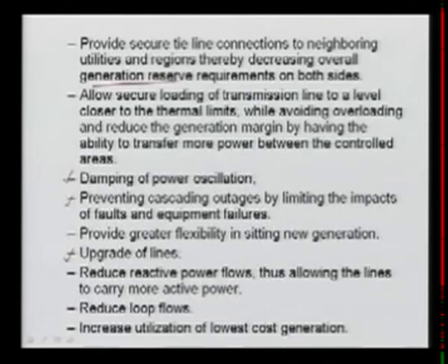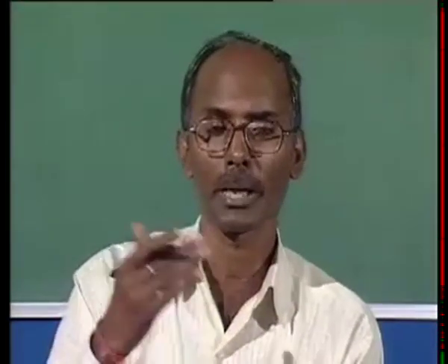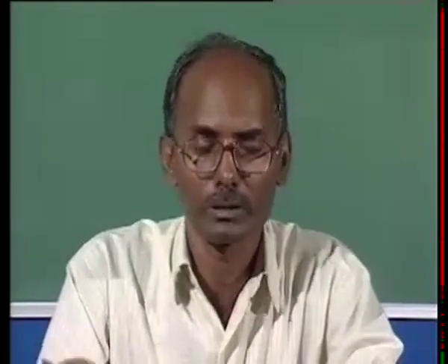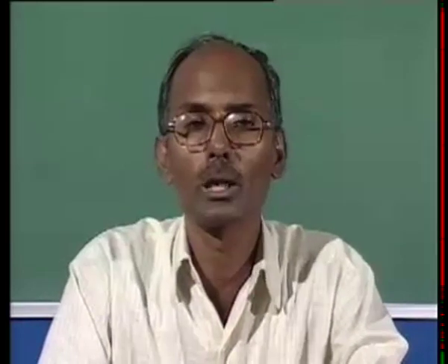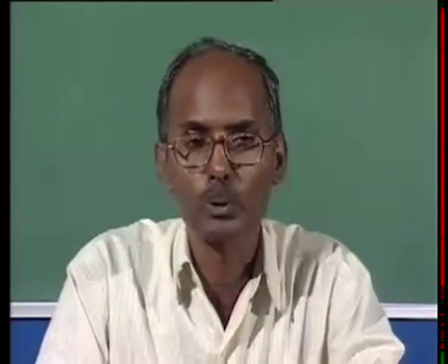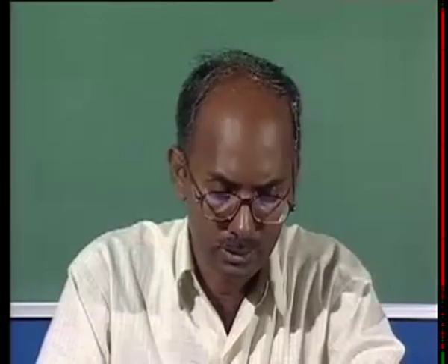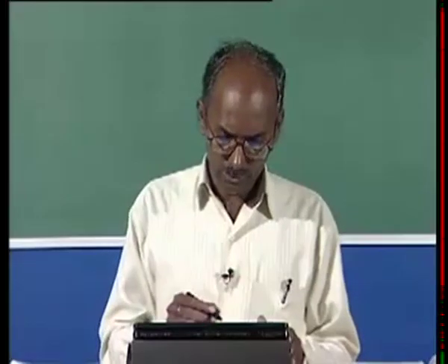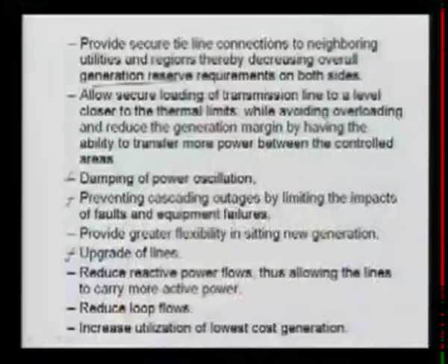Another is upgrading of the lines. That means at the same time you can go for the upgrading of the lines, from one conductor to the other size of conductors, and then you can load up to that limit by using the FACTS controller. It also reduces the reactive power flows, thus allowing the line to carry more active power. So it can reduce the reactive power in the transmission line